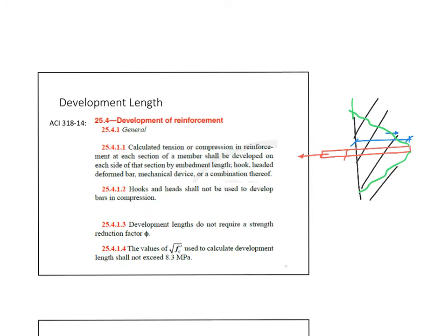They have to do with the strength of the bar, which is this here, and the strength of the concrete, which is this here. But then the third failure, which is a really, really bad failure, is if I failed the bar in slippage, which means the bar is pulled out like this. Now, this is the failure I cannot accept.